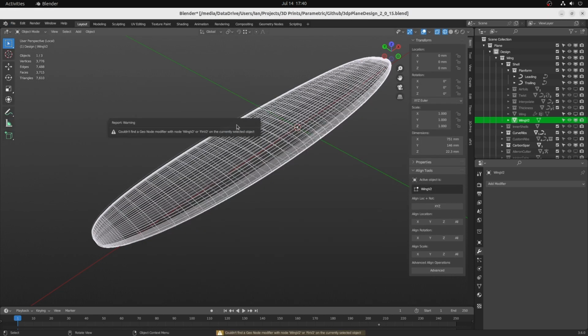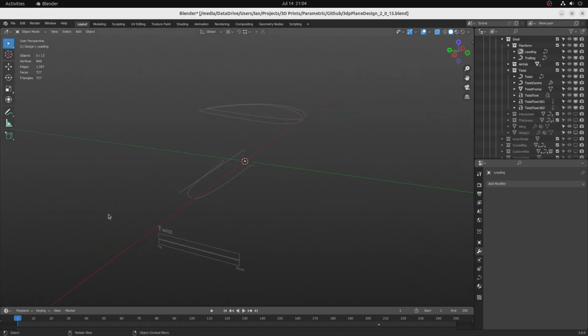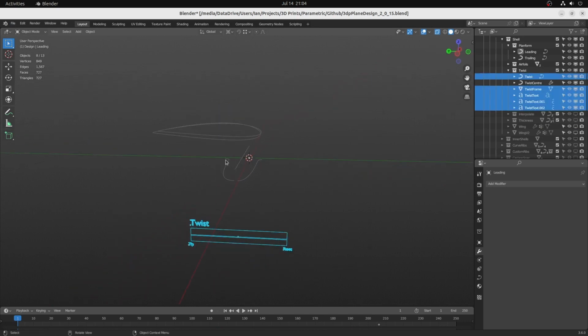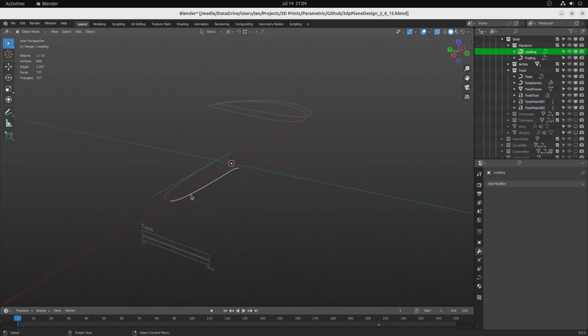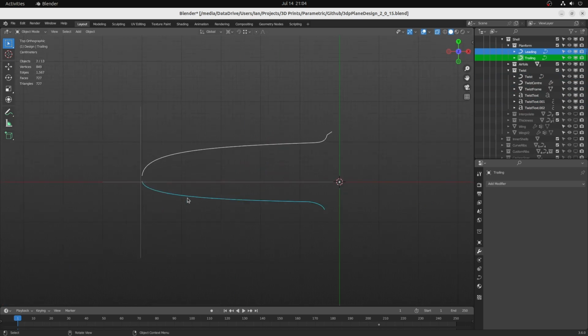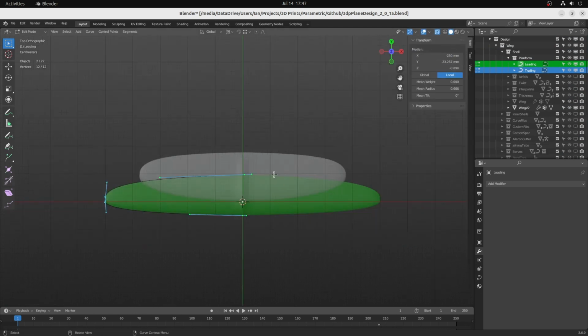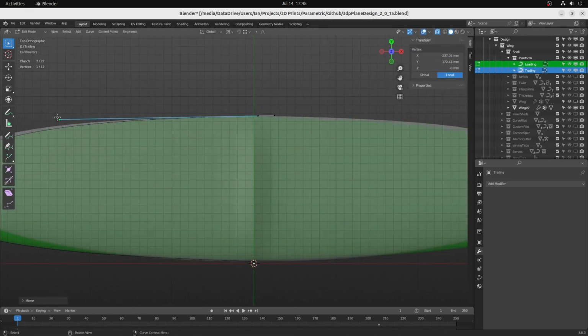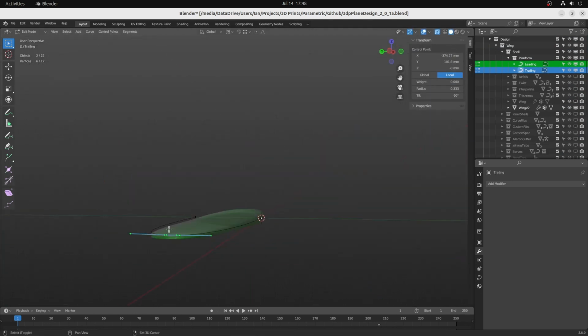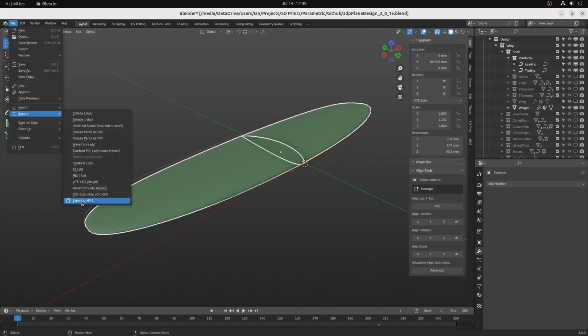The add-on doesn't export the actual wing geometry directly. It exports the airfoils, the twist, the planform shape and the dihedral data, which the Blender geometry node tools use to build the wing shape in Blender. It's not all bad though, as long as your wing design is reasonably conventional. It should only take a very short time to recreate it in enough detail to do the export.